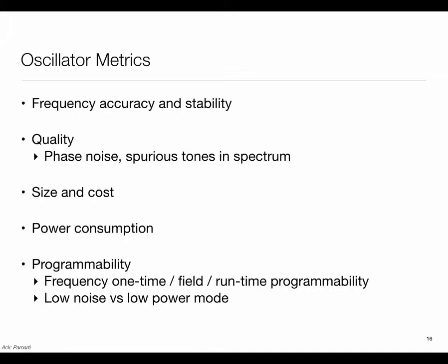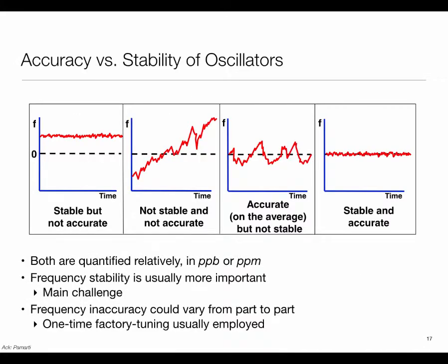For example, many of our systems we put into sleep, and you don't want the clock to become a hungry source. For example, a lot of wireless sensors and these tiny devices, even things like Fitbits and the like, they usually are heavily duty cycled, and you want to make sure that clocks do not become power hungry. And the longer the duration you need to maintain time for, the more stable clocks you need, but stability comes at a price. Very stable clocks could be extremely expensive or extremely power hungry.